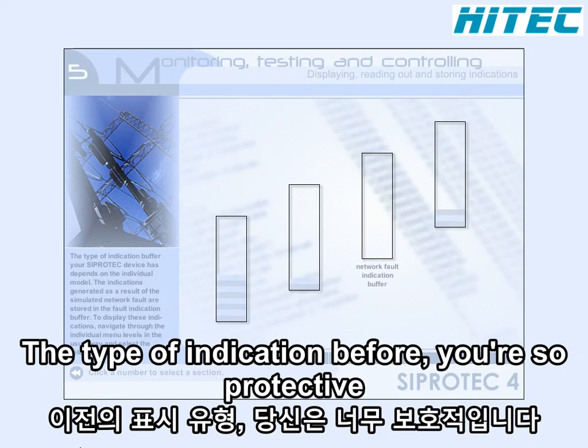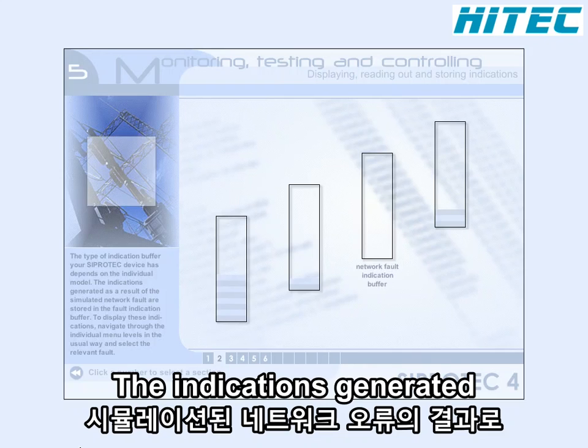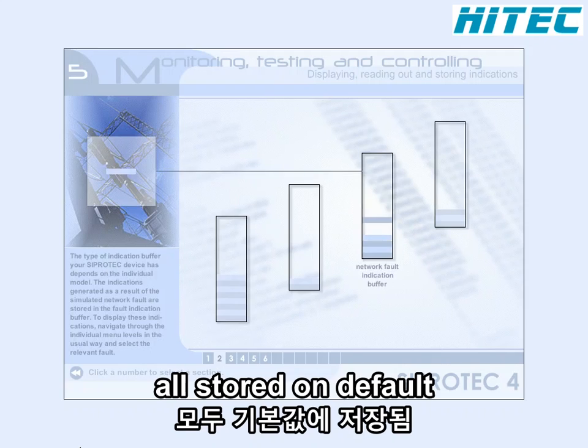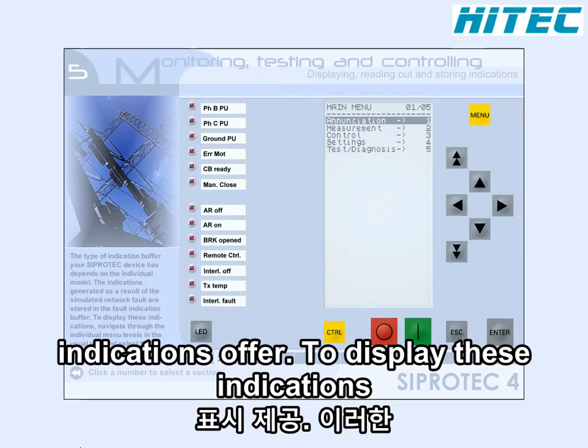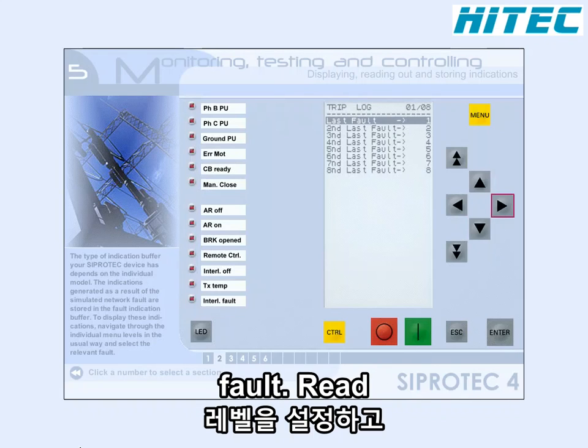The type of indication buffer your SIEMENS device has depends on the individual model. The indications generated as a result of the simulated network fault are stored on the fault indication buffer. To display these indications, navigate through the individual menu levels in the usual way and select the relevant fault.